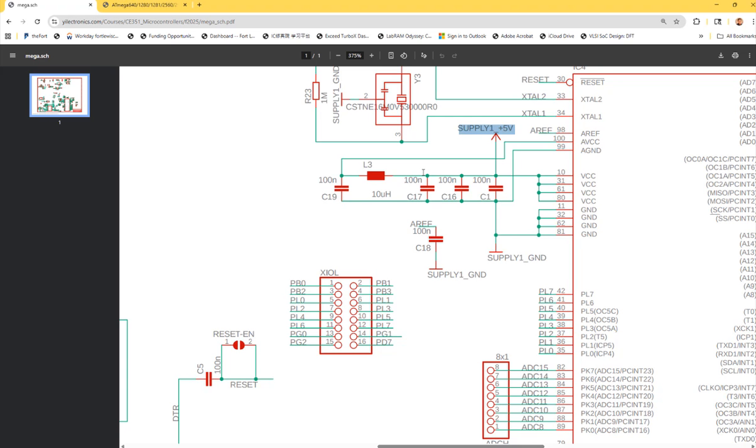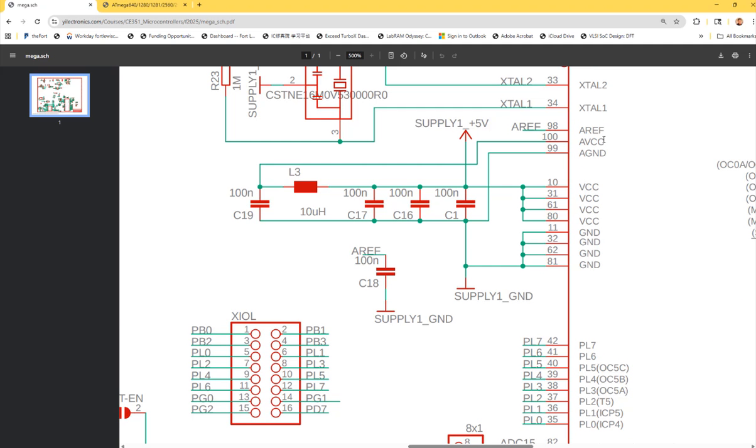So AC signals by chance comes through this capacitor from the ground will be rejected by this guy. Or you can say maybe any AC surges, because sometimes the power supply is getting affected by the signals, right? If it's not stable at the point, and this will reject it, so it's not being sent to AVC. So why we worry about AVC here? Because AVC is a reference voltage being used for the ADCs, and usually you want to keep the resolution and sensitivity or quality of the ADC conversions, right? So get rid of a lot of noises from the ground, and that is why you are shorting this one to the inductor, right? So you can isolate this stage from this power supply stage for the ADC's reference voltage.